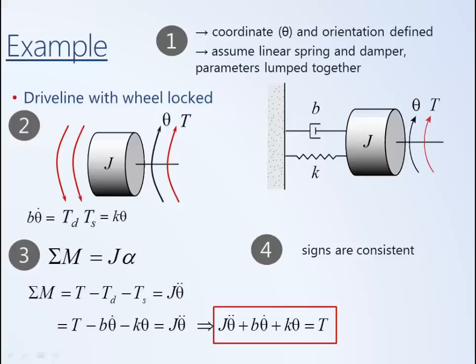And so that very quick jump in torque can excite high frequency resonances in the driveline, whereas an IC engine is slower to respond, and it's less likely to excite some of those resonances. So that's another reason why it's especially important to be able to model and analyze the driveline in an electric vehicle.